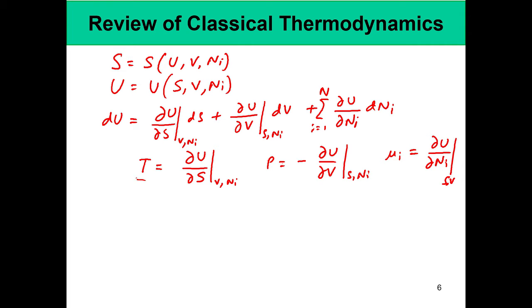In other words, when T in two different components of a system which are separated by a non-adiabatic wall are equal, there will be no heat flow. Similarly, in a system separated into two parts by a flexible wall which can move, if the pressure P in the two components is equal, it can be shown that mechanical equilibrium is attained.